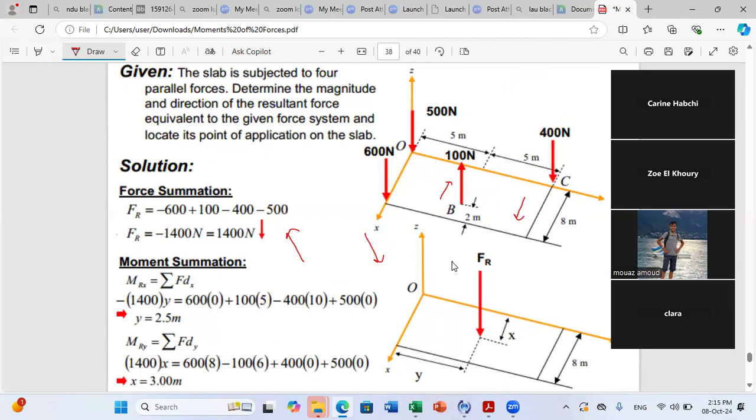Exactly. So if you know the plane of the forces, no need to work with cross product or vectorial product. You just say one method is the following. I find the perpendicular distance between the two forces. And here I cannot take any distance in this method. I take the perpendicular to say that the magnitude is F times D. So for the magnitude, you cannot take any distance between 2 points.